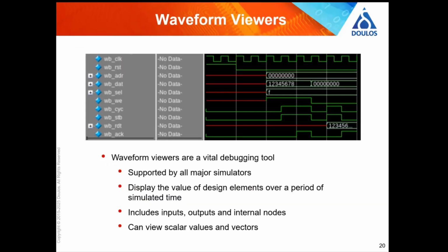And how do we know that the design under test is doing the right thing? Well, in a very, very basic test bench like this, and this is extremely basic, in my opinion, too basic, we would fire up some kind of waveform viewer and eyeball the waveforms. This is the kind of thing that you might do when you first design something. So you just want to do some kind of sanity check, some kind of smoke test to make sure that your design really is vaguely working.